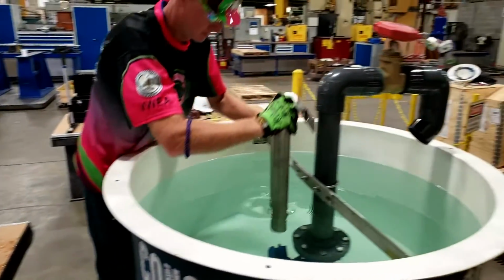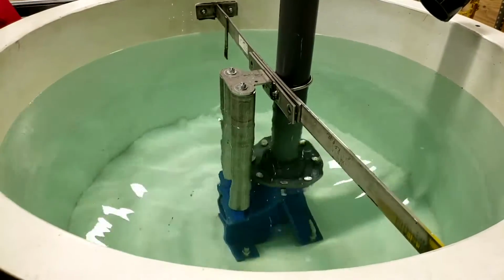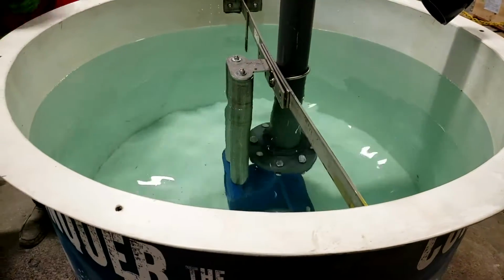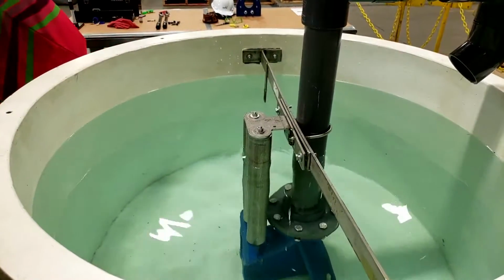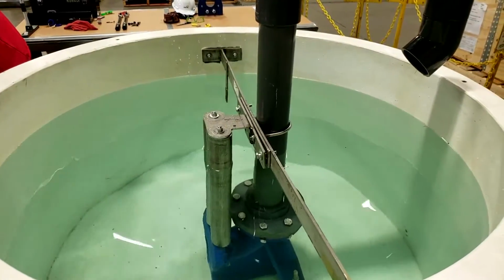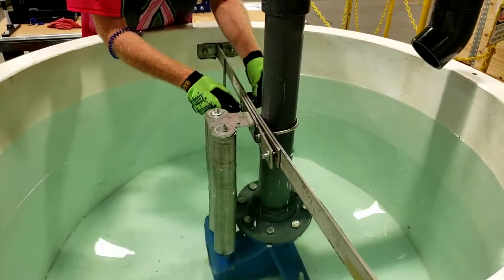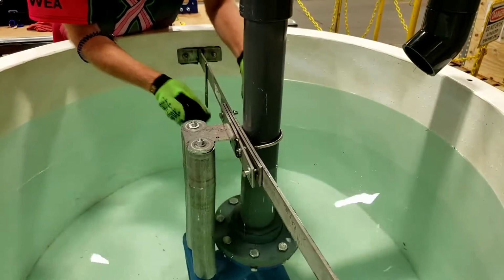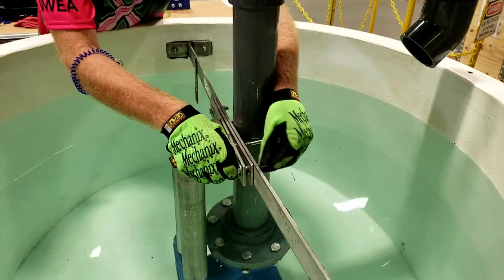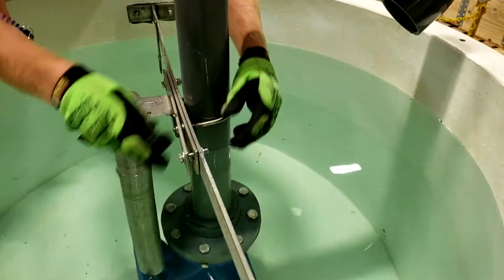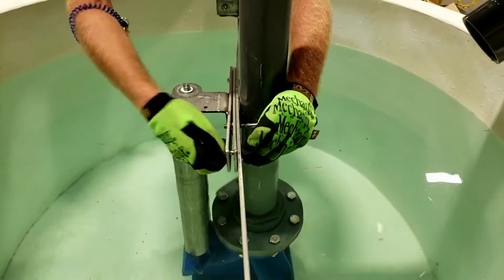You will reuse the same 9/16 inch bolt, washer, lock washer, and nut to attach the flange to the cross member in the wet well. Ensure that the standard washer is on the bolt head side and the lock washer is on the nut side. These shall be tight enough that there is no gap between the flange bracket and the cross member, and they cannot be turned by hand. Ensure the bolts are installed such that the head of the bolt is on the same side of the flange as the guide rails.